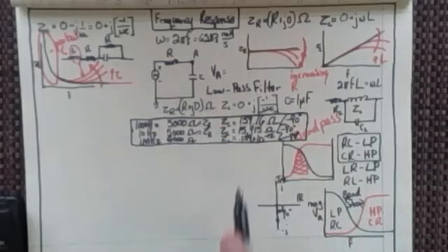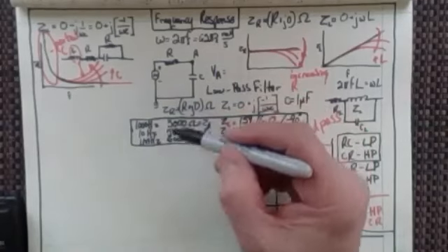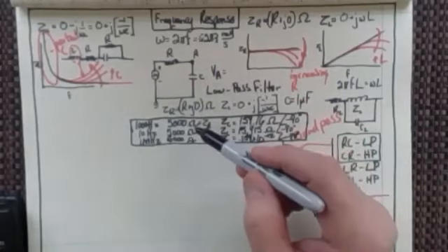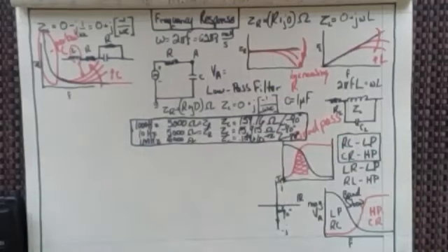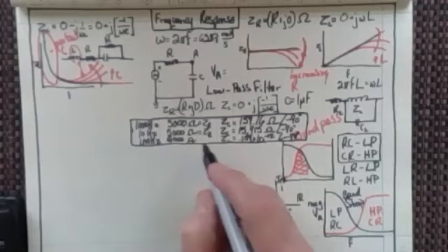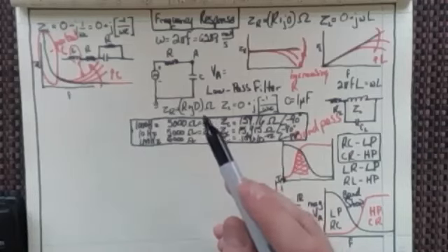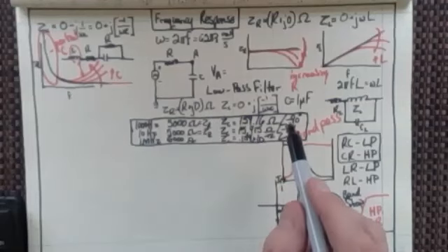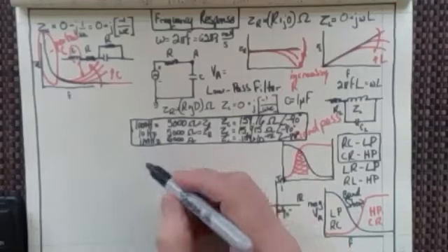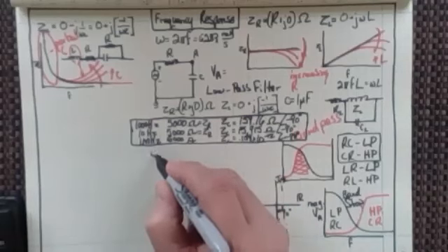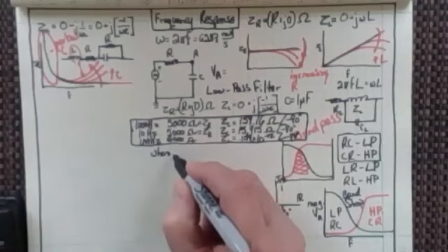So I think everybody can see what I was pointing out: at the higher frequencies, you're going to have the resistive loading impedance. At the lower frequencies, you're going to have the capacitive impedance that predominates. So now let's look at this, because what I really want to find out is where R equals X sub C, right? So where does